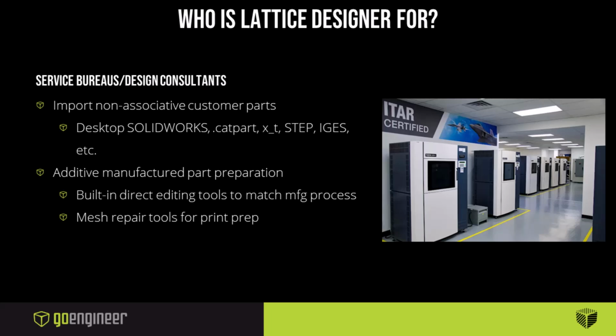So if you used, for instance, CATIA visual scripting, then you can do things like create your own various 3D nodes inside of visual scripting, connect it with Lattice Designer, and have your own implicit modeling customized setup done there. One of the apps that we didn't touch on is the 3D printing preparation app as well. That will let you modify meshes and heal and fix faces to make sure a part is watertight and prepared for 3D printing as well.